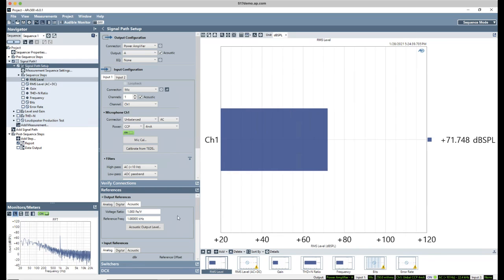I think that perhaps my setup is not quite right in my remote environment, but that is actually an opportunity for me to show you a different way I can do this. So normally I would have calibrated this so I get 94 dBSPL of output, so I can then make all my measurements relative to that. But I suspect somebody has moved a microphone or speaker in my test lab. And so instead, I'm going to make my measurements relative to my measurement mic.